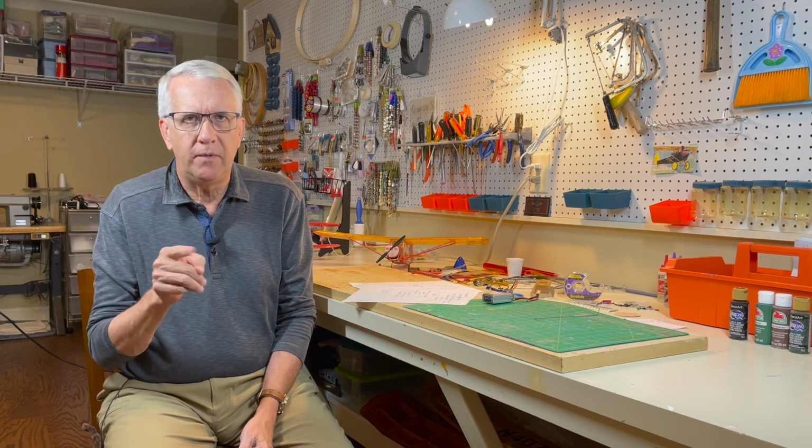And that's another little bit of a range discussion, because as the fuel burns out, the model will become a little bit more tail heavy. Hopefully it falls within the center of gravity range for that model. So CG is important. Check it before every flight, check it as you build, and good luck with your RC flying.